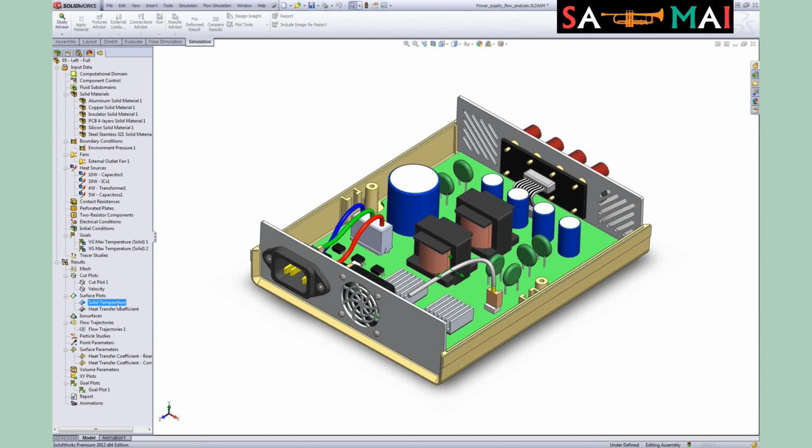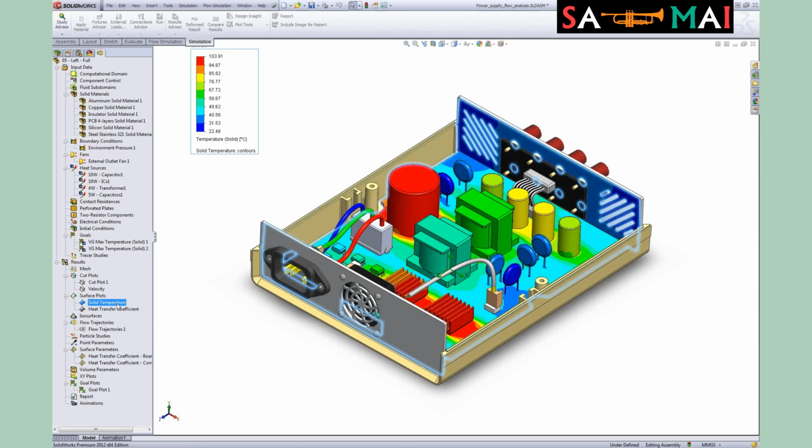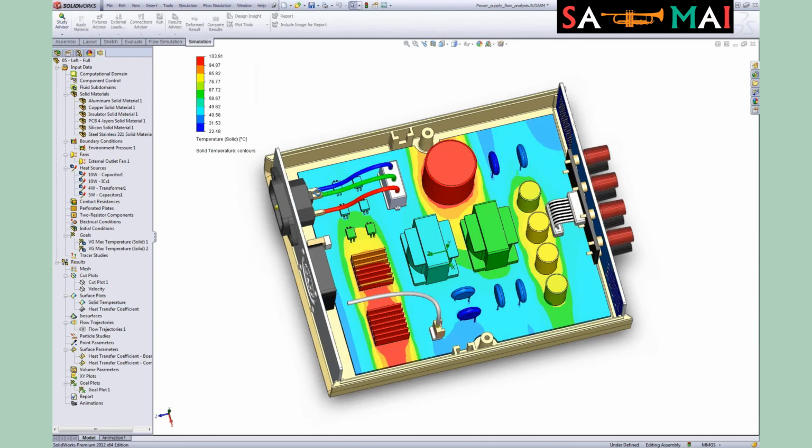But any questions up to this point? Okay, actually one of the questions is, can you enter your own fan curve into the fan module? That's actually a very good question. Yes, it's fully customizable. So if you have that empirical data from the fan, either from the fan manufacturer and it's not one that's in the list, or you did that testing yourself, let's say you set up pitot tubes and pressure sensors and everything else to get that kind of data, yes, you can enter that in, and I'll actually show you that here in a minute.